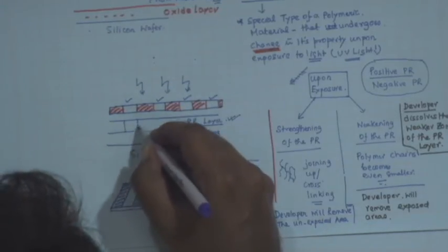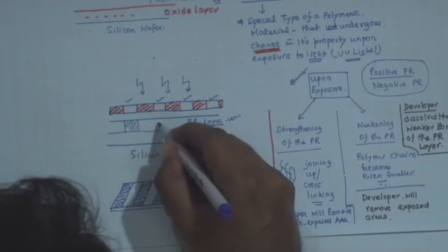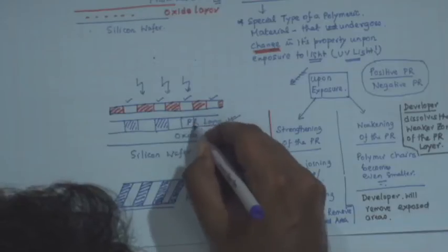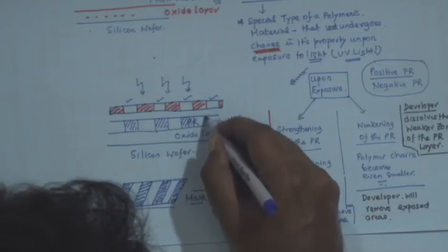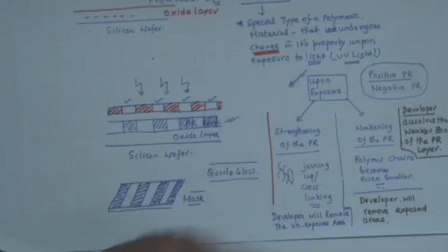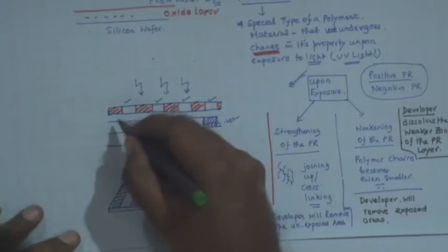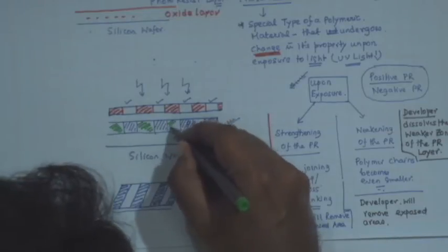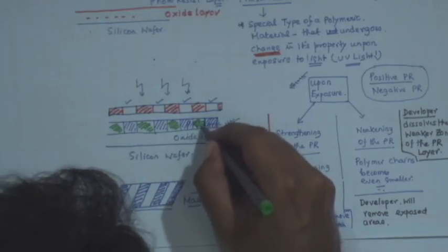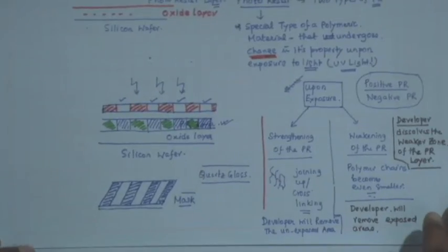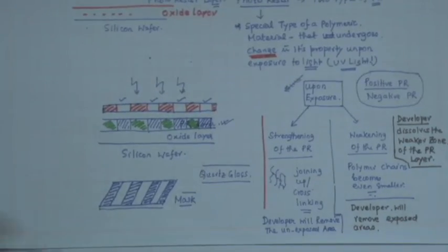Along the contours of the patterns of the mask, these areas in the photoresist film are going to be exposed and change property, while the other areas do not change property. However, they are roughly the same material. So, your developer has to be very selective to only the weaker part of the photoresist formulation.